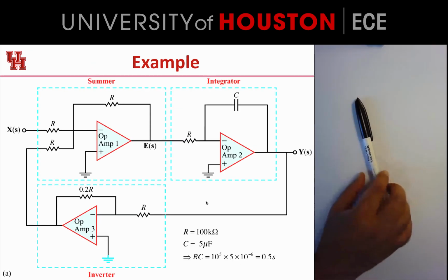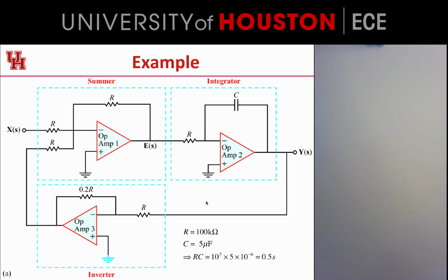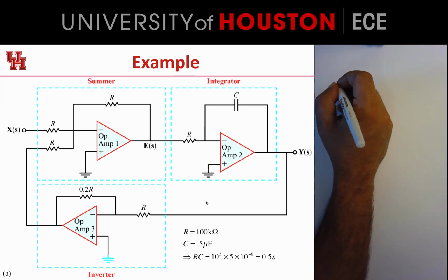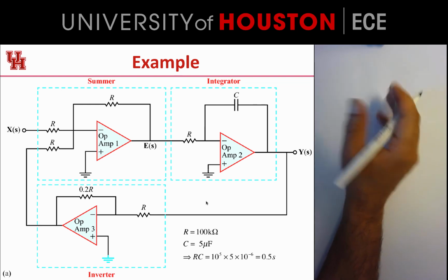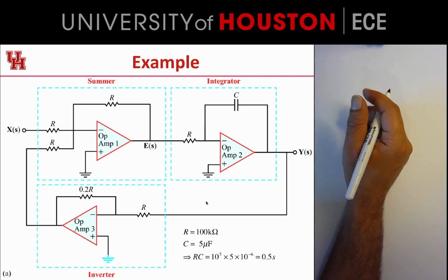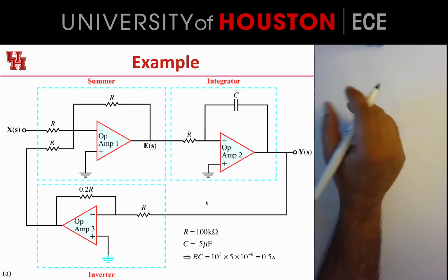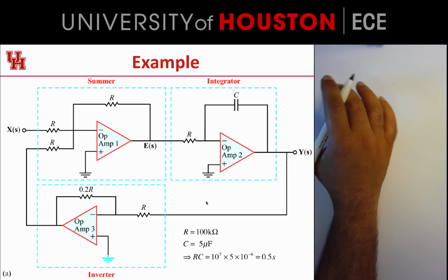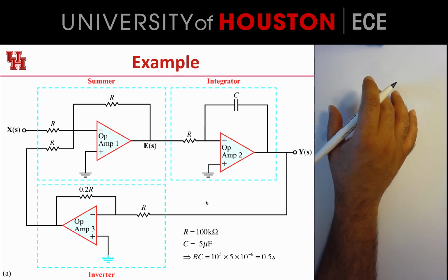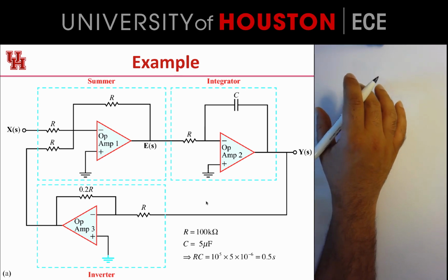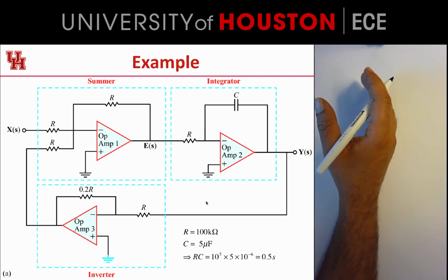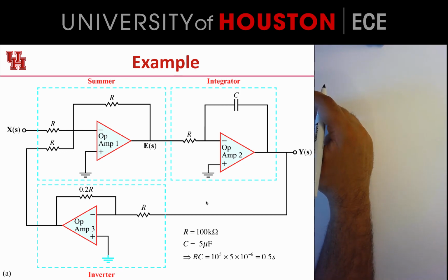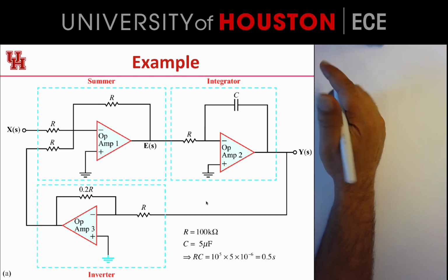We're given this very complicated looking circuit. It's got three different op amps, op amp 1, op amp 2, and op amp 3, and we have to figure out how to deal with this. One strategy is to start to recognize some of the standard patterns. What you see on the upper left is basically an inverting amplifier, but this one has addition capability, so it's got two different inputs.